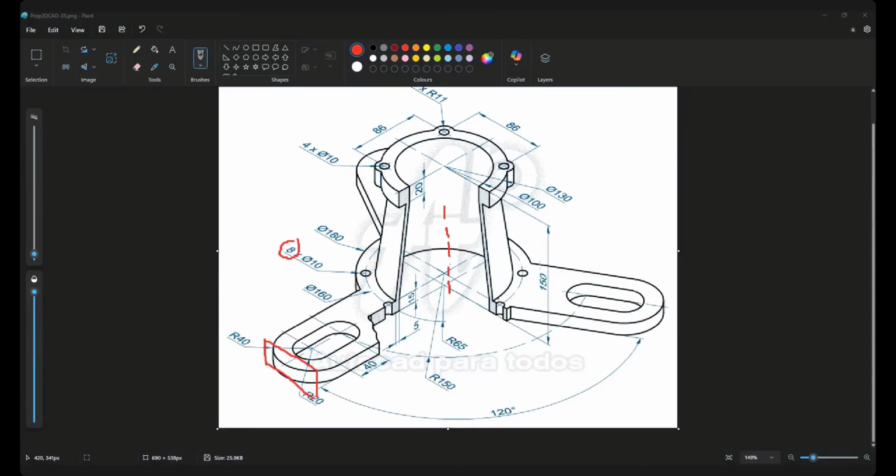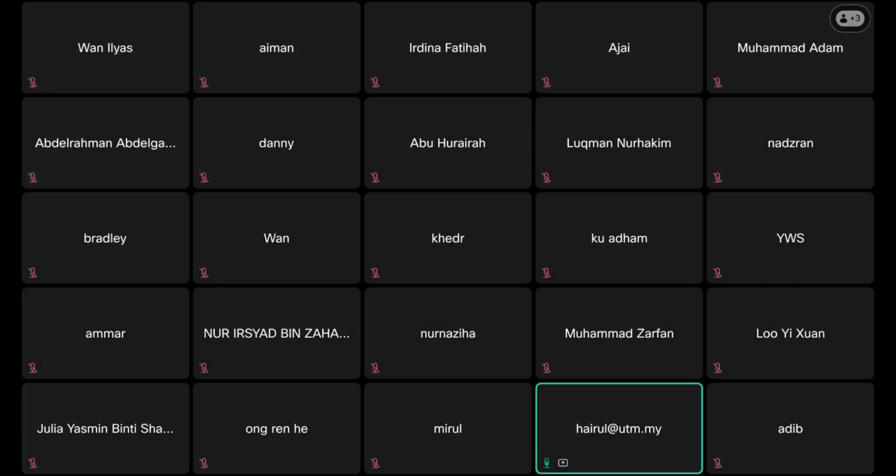You have this plane, right? This flat plane. You create sketch. Then you must create the circle of radius 80, right? Do you understand, class? Yes. Radius 80. I don't want to show, you figure it out. Click sketch on this plane, then perpendicular view, draw a circle from that center of the cylinder, radius 80, and center line. Okay, center line.